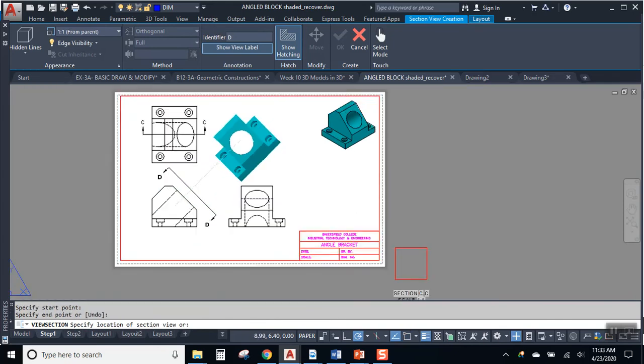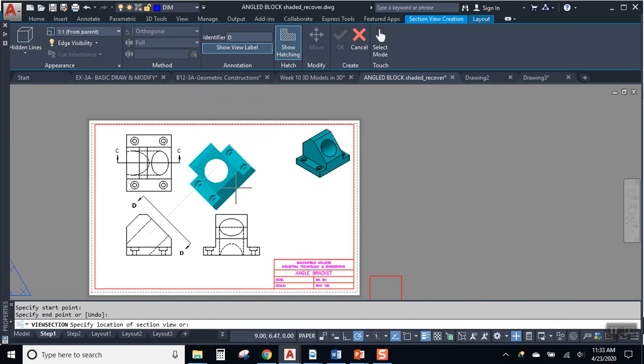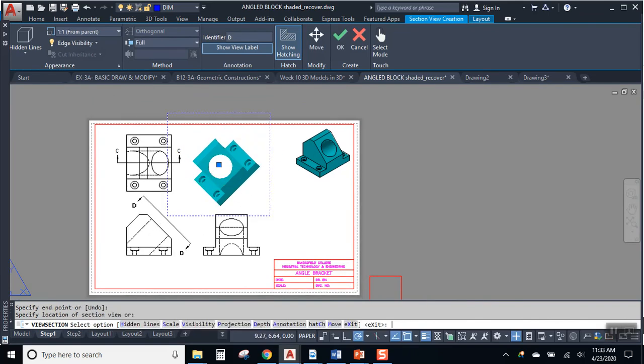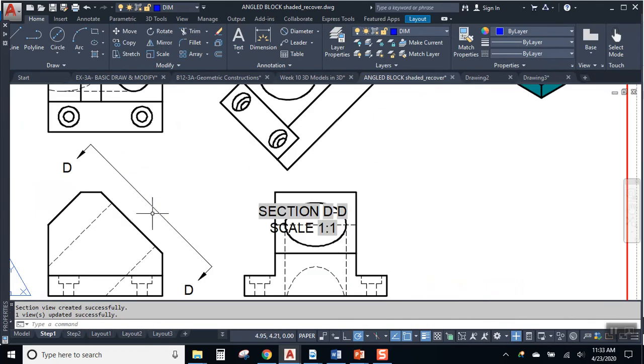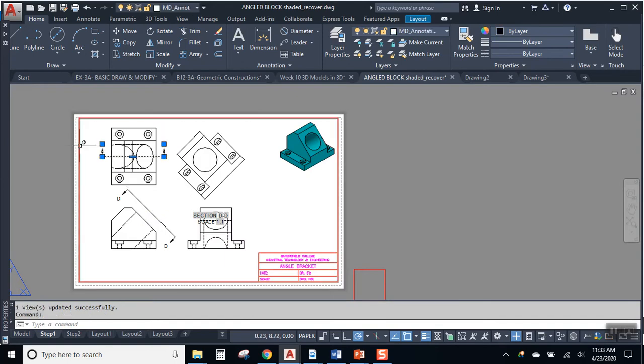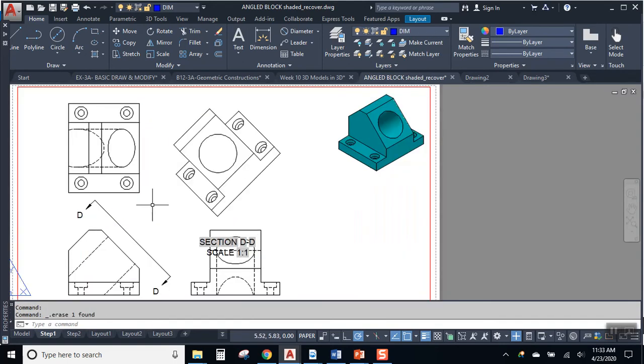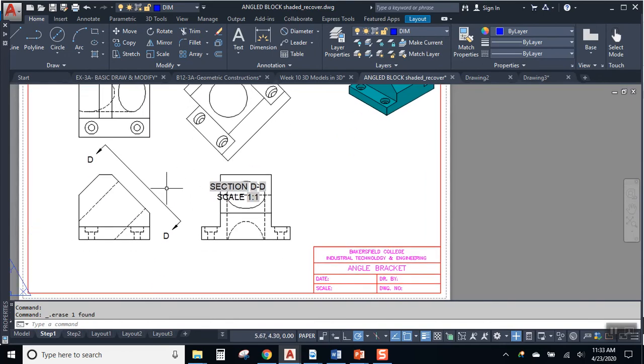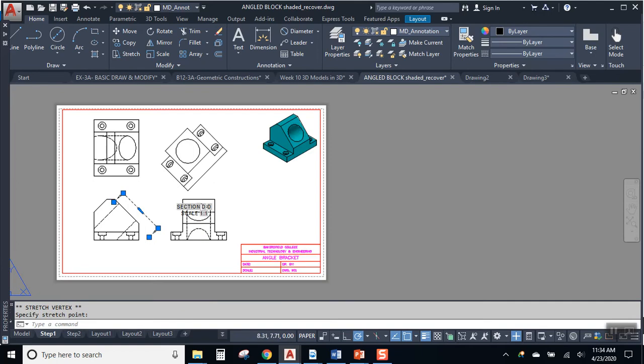And doing that's not that weird. Actually, when you draw a cutting plane out in space, it's called a viewing plane. So now we're looking at things instead of cutting through things. All right, so this cutting plane is creating this auxiliary view. Now be careful, if your cutting plane is too small, it will cut off part of your auxiliary view. Okay?